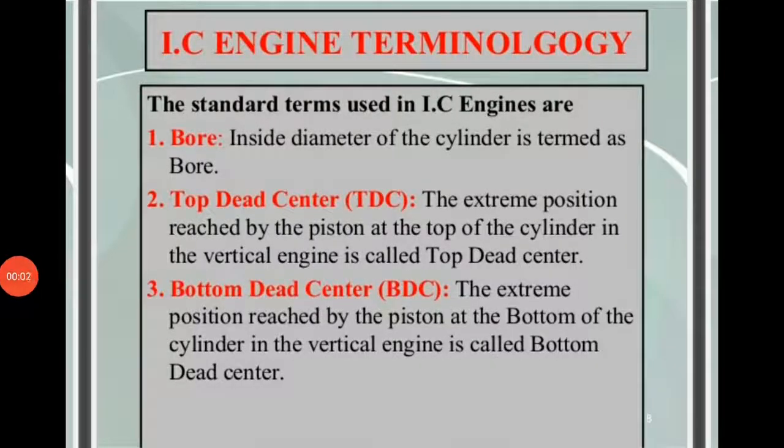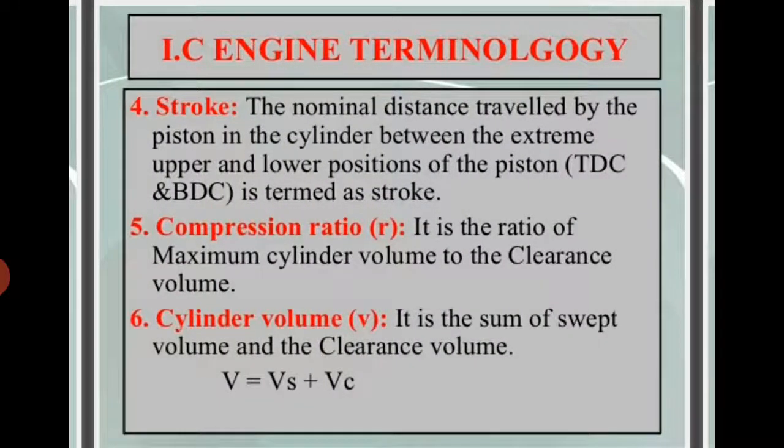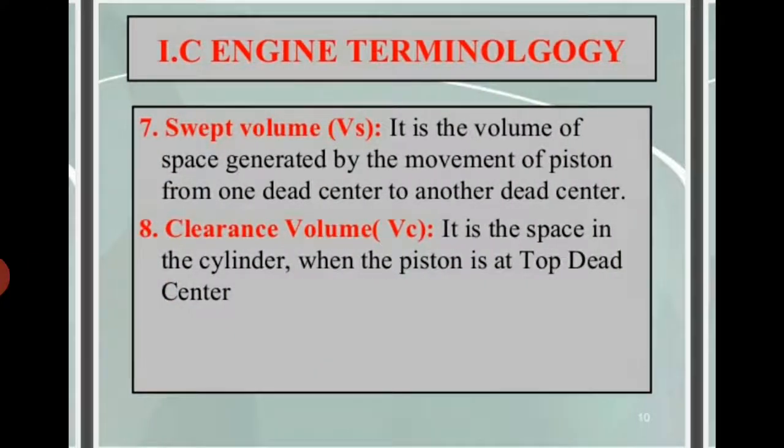Hello students, good morning. In this lecture we will study IC engine terminology and the working of the 4-stroke diesel engine. First of all, we will discuss IC engine terminology. In this topic we will study bore, top dead center, bottom dead center, stroke, compression ratio, cylinder volume, swept volume, and clearance volume.